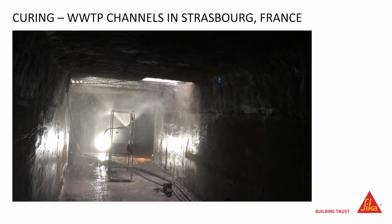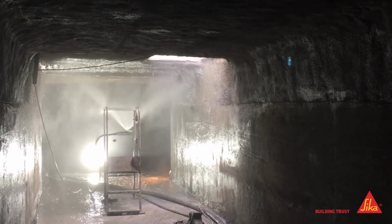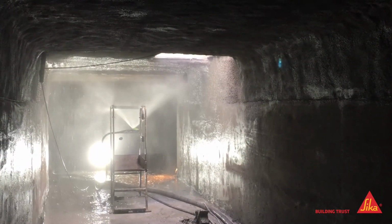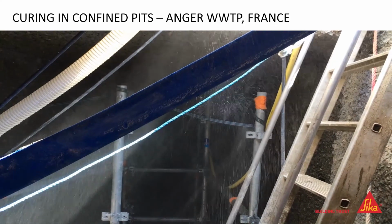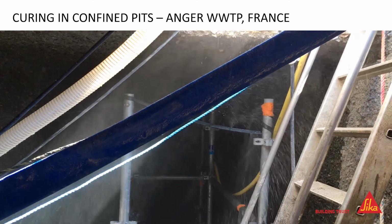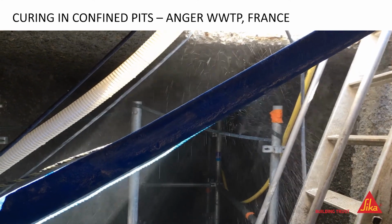This slide shows an example of pre-wetting and wet curing in a channel of a wastewater treatment plant in Strasbourg, France. This is another way of pre-wetting and curing the concrete surface in a very small congested confined pit in a wastewater treatment plant in Angers, France.